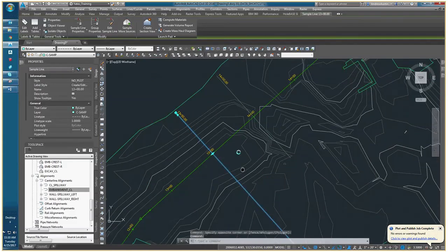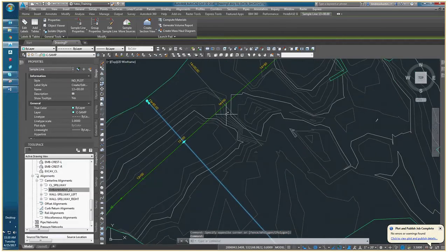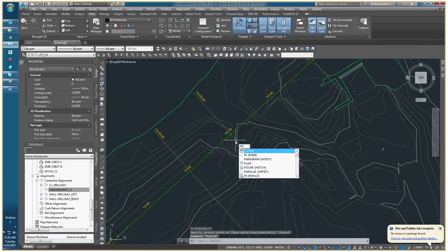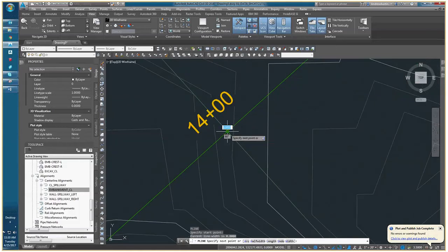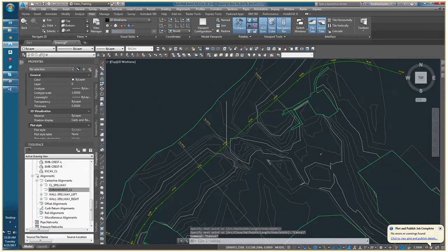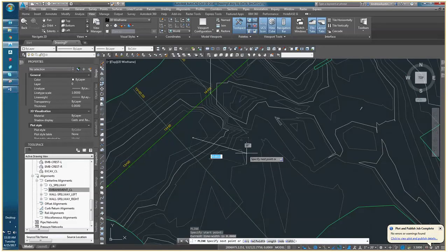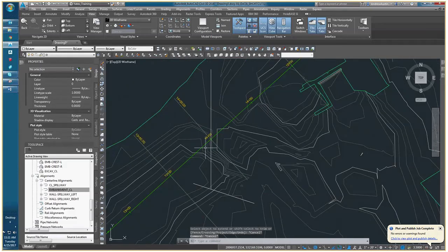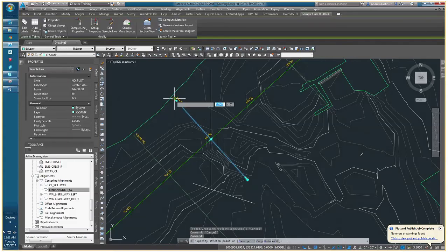There are special cases, and I will say it's very, very rare, when we will need to show skewed alignments. I suggest that you create some representative line work with a polyline on the defpoints layer to use for this. Again, it is a very rare case, but perhaps you have a pipe or something that's coming through this alignment at an odd angle, and you want to show what the existing or proposed ground is doing.